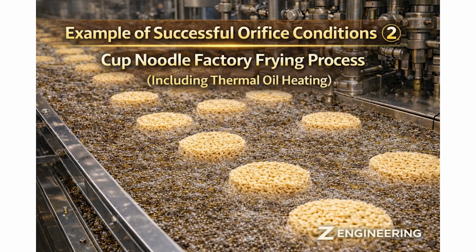Next example, a continuous heating line in a food factory. For example, a fryer line used in instant noodle production. The production line runs at a constant speed. The process does not stop. The throughput is stable. Steam consumption stays within a consistent range. That means condensate flow is also stable. These conditions satisfy the requirements for an orifice trap.